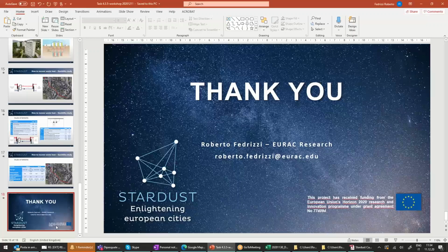So I noted two things I wanted to ask you. You mentioned it works with low temperature district heating. This is not the case for Kozani. It's operating, if I'm not wrong, at a bit less than 90 degrees, with returns of 60 and 70. So my understanding is that it might not work here.